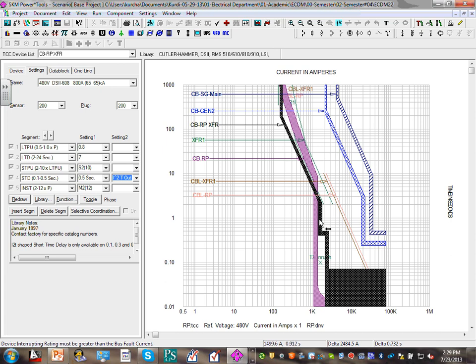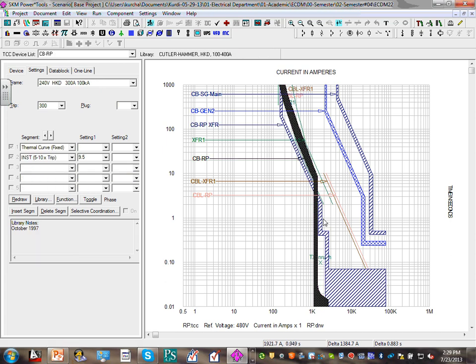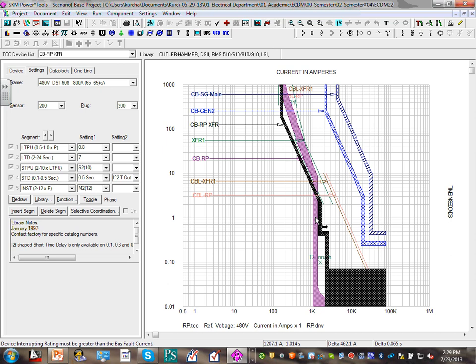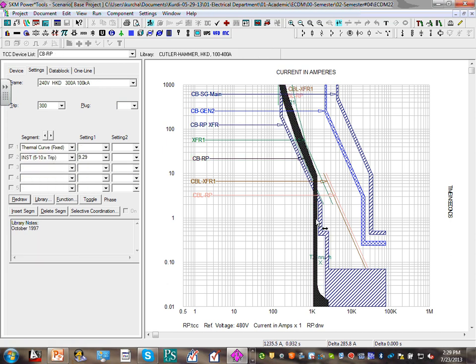But sometimes it's really hard. I don't know if you guys, Dave, find it very hard if you use two different types of circuit breakers, hard to coordinate between the primary of the transformer and the secondary. But who cares? You do your best, because if the primary trips or the secondary trips, the outcome is you lost the receptacle panel. You try to do the best that you can in terms of coordination between primary and secondary of the transformer.